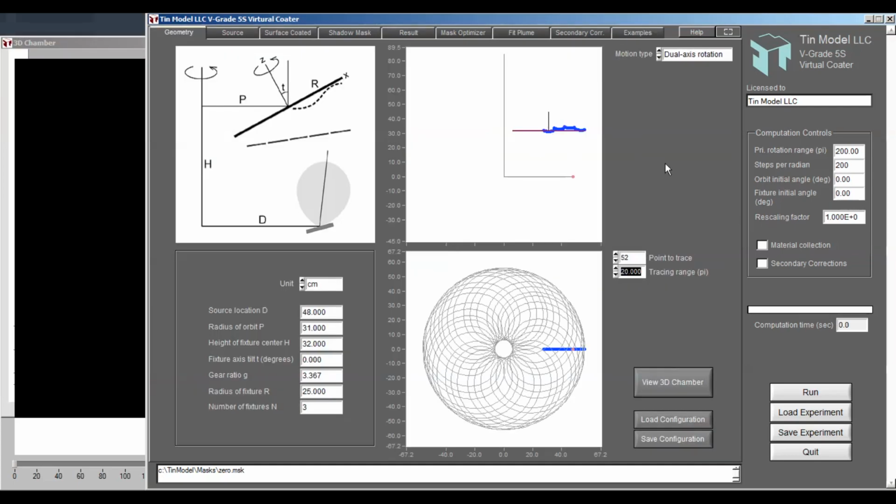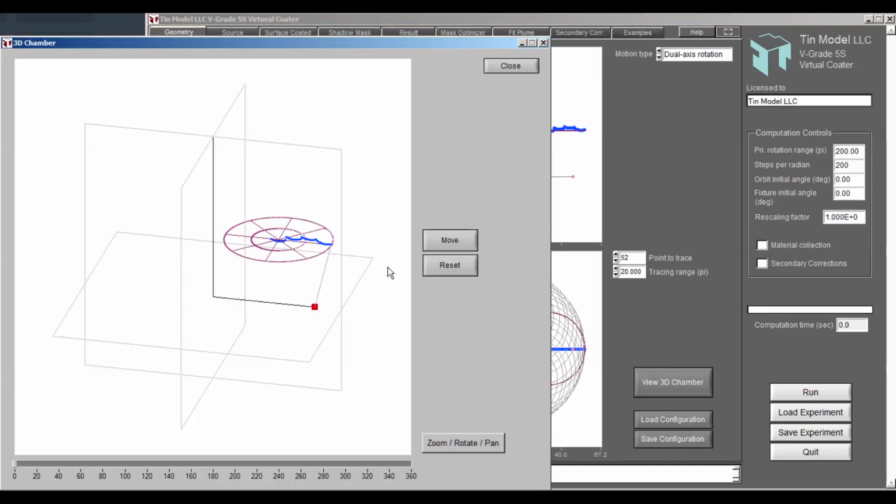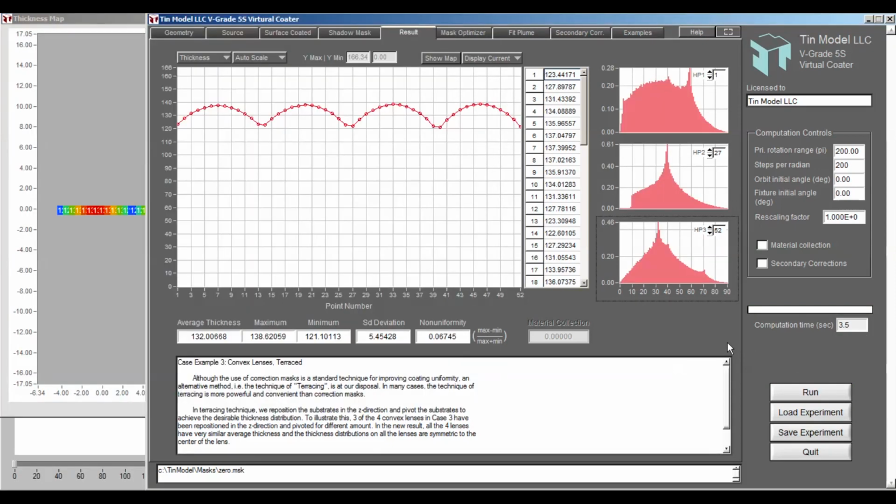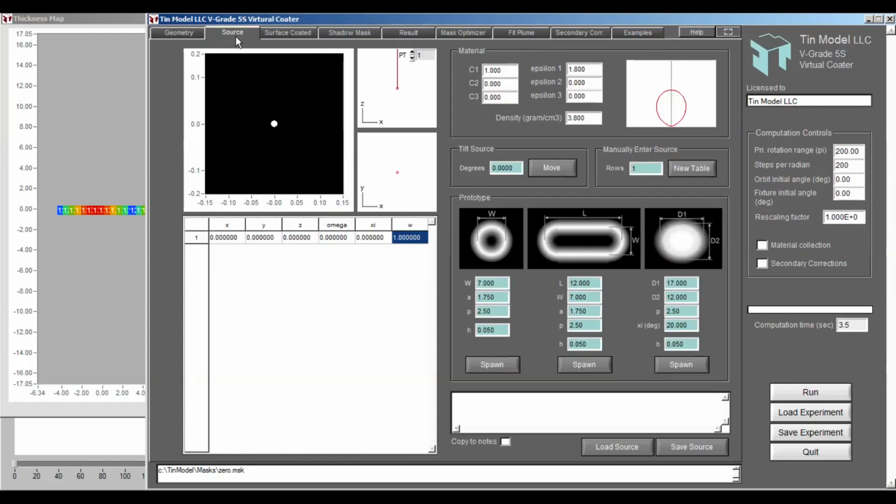Your sputtering sources can be of any geometry: planar, cylindrical, hollow cathode, etc. The software also predicts how erosion of a target will affect thickness distribution. You can even model some absolutely unique, one-of-a-kind thin film deposition processes.